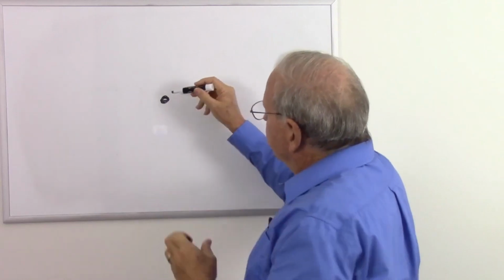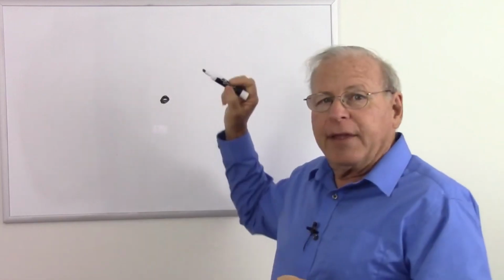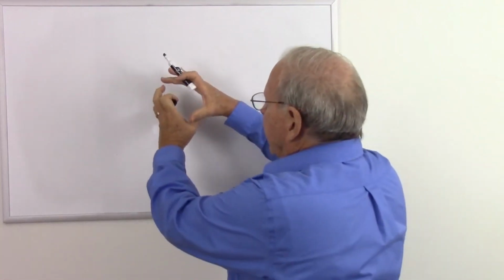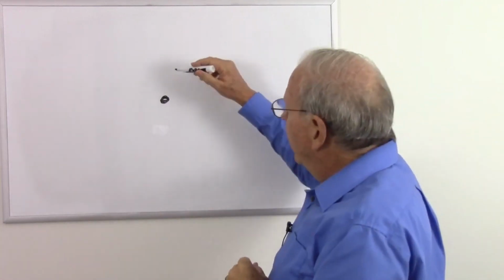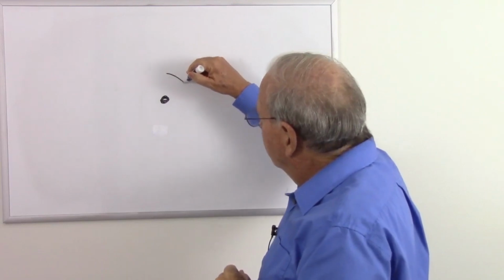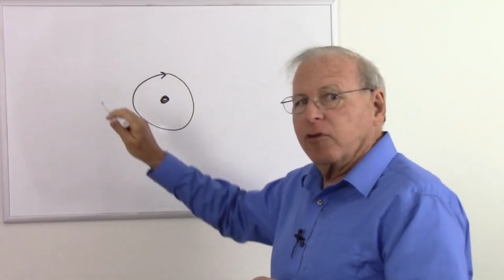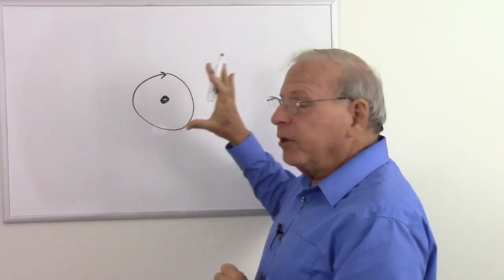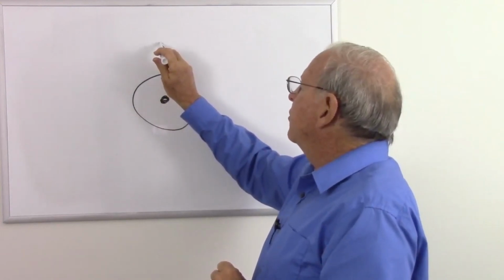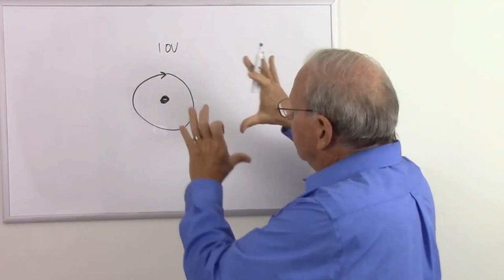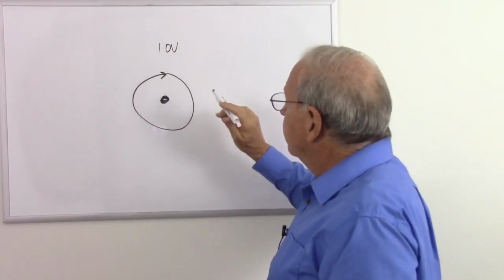And let's say that right now, because of the direction of the turns of the coil and the direction of current in them, and the fact that the magnetic field is building with a certain polarity, at this moment in time we have an electric field that wants to cause electrons to move in a circular path going clockwise. And at this particular moment in time, that electric field has a total of, let's say for convenience, 10 volts. So there's a total of 10 volts in this field, and we'll see how that works out in a couple of moments.